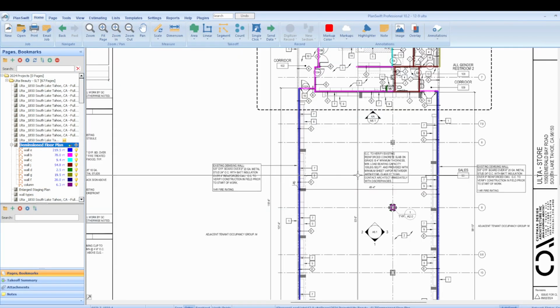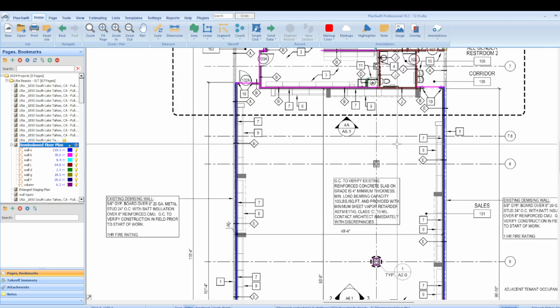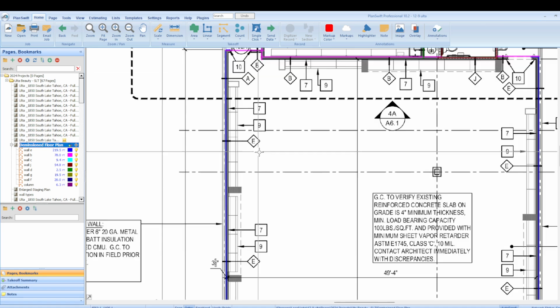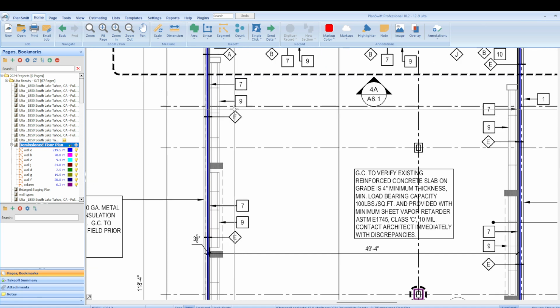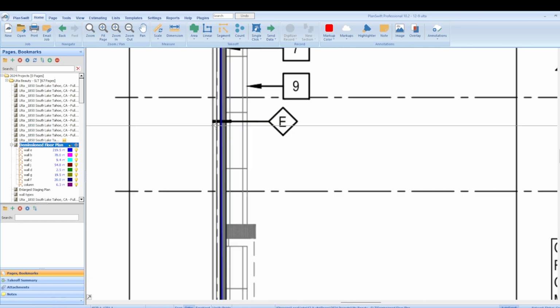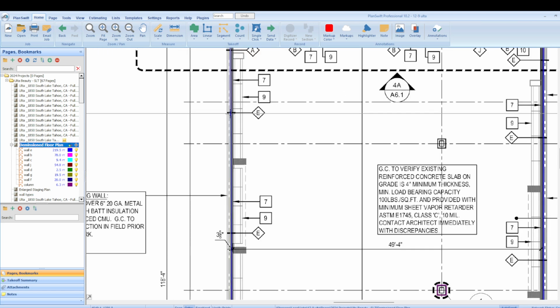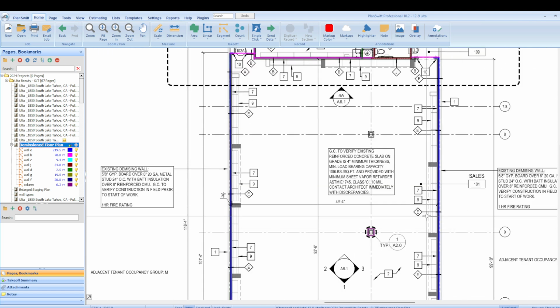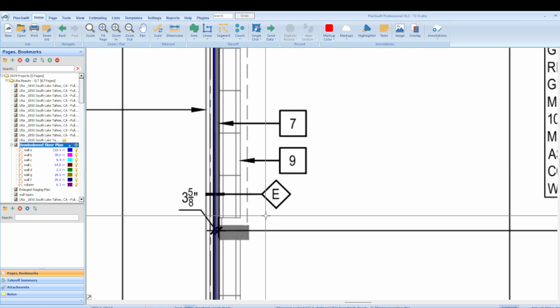Everything in your architectural set is going to tell you either what something is or to do something. So when you look at your symbols and your lines, you have to be able to determine what this symbol means as opposed to the square. When the square is tilted, what are we doing? Oh, it's going through this line. What does that line mean? Here we're showing a representation of all of the different walls, and these are wall tags.